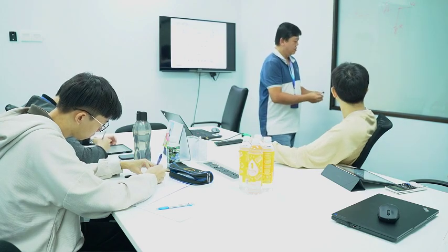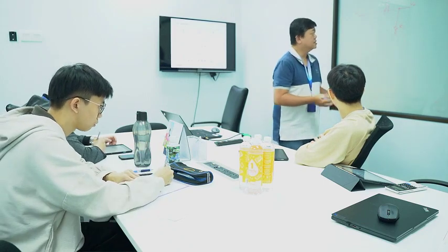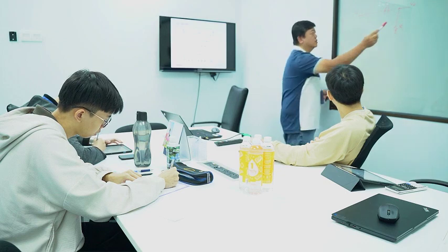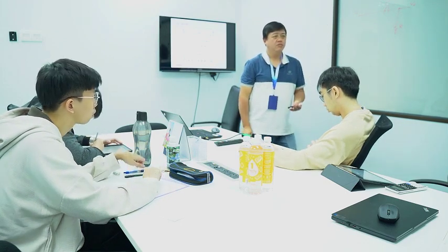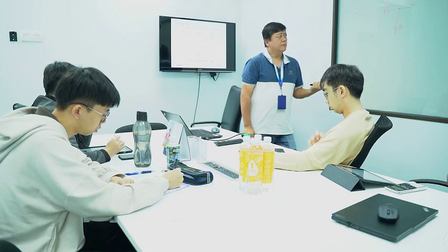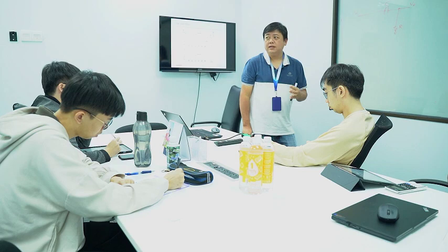Okay, now whenever you do the AC analysis over the transfer function. Transfer function means that we take your output divided by input. We call it TF, transfer function, or we can say it is a gain. Your output divided by input is a gain, right? It can be voltage gain, it can be current gain, but in this case, a voltage gain. Very important, huh? And whenever people ask you, you must not just say it's a gain,